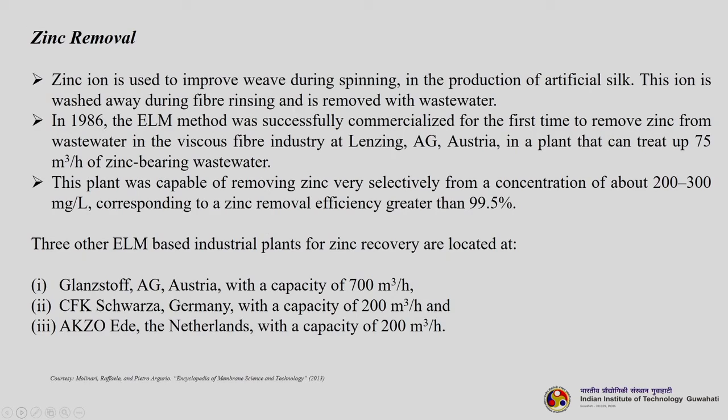So, another example is zinc removal. Zinc ion is used to improve weave during spinning in the production of artificial silk. This ion is washed away during fiber rinsing and is removed with wastewater. Zinc is highly toxic. So, in 1986, the ELM method was successfully commercialized for the first time to remove zinc from wastewater in the viscose fiber industries at Lenzing AG in Austria, in a plant that can treat up to 75 meter cube per hour of zinc bearing wastewater.